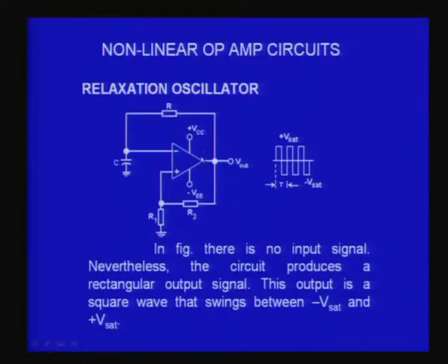You see on the screen you have an operational amplifier, which could be in this case 741 operational amplifier, and you see the plus terminal is connected to R1 and R2, and immediately I hope you can imagine that this is a regenerative comparator. That means it will have a hysteresis associated with that. The low tripping point and upper tripping point will be on either side of 0. One will be plus some voltage and the other will be minus some voltage.